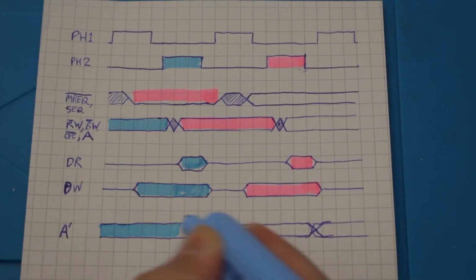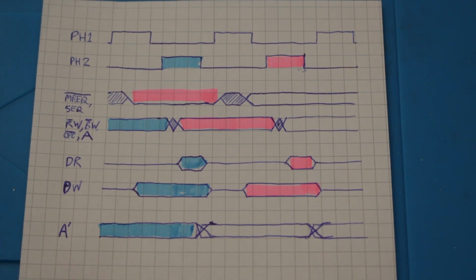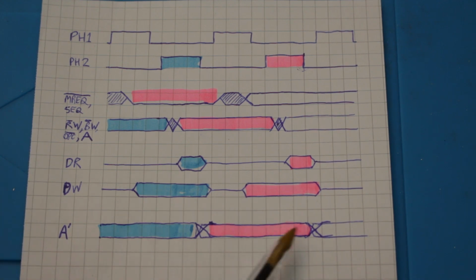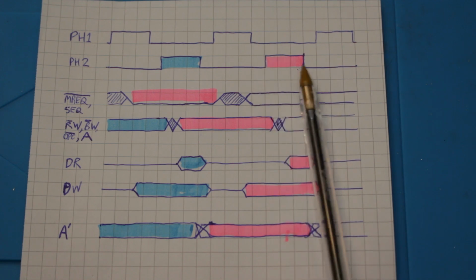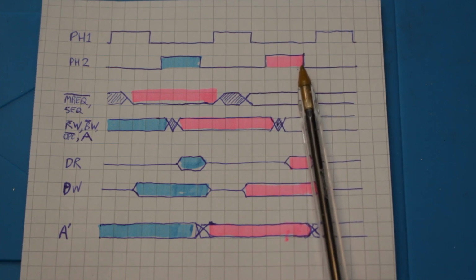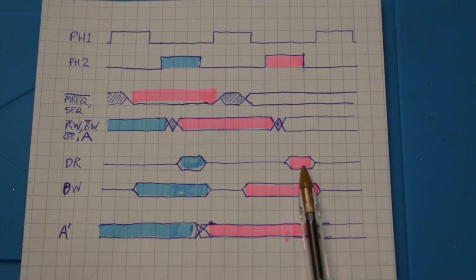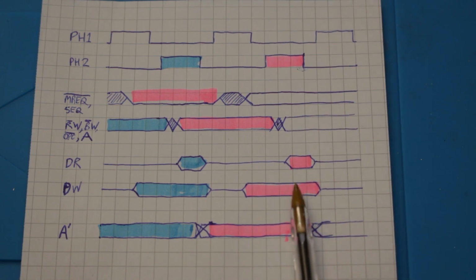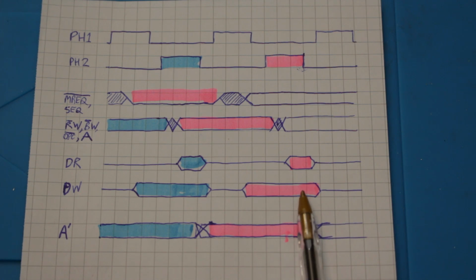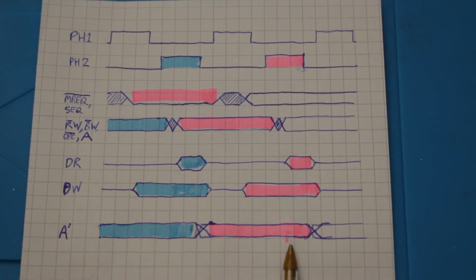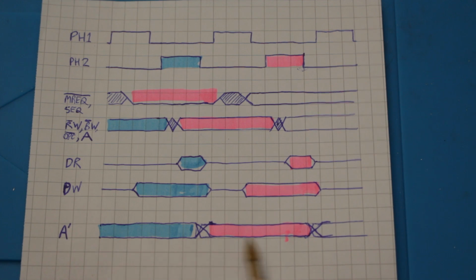And if I now draw on the colors for these different addresses, you can see straight away that that's going to be much more useful to us, because now we have this period at the end of phi 2, the trailing edge of phi 2. We simultaneously have the period when we need to be providing data to the CPU, the end of the period where the CPU is providing data to us, and the address still being valid on the bus. So that's really helpful, and essentially this address latch enable pin means we don't actually need to latch the address.